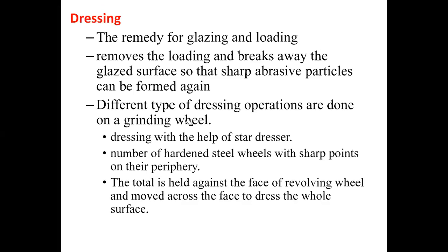So removing the loading and breaking away the glazed surface so that sharp abrasive particles can be formed again, this process is called dressing. Dressing is nothing but removing the glazed layer that has formed on the surface. When you remove the glazed layer, the inside of the wheel is exposed on the surface of the grinding wheel. This is called dressing.